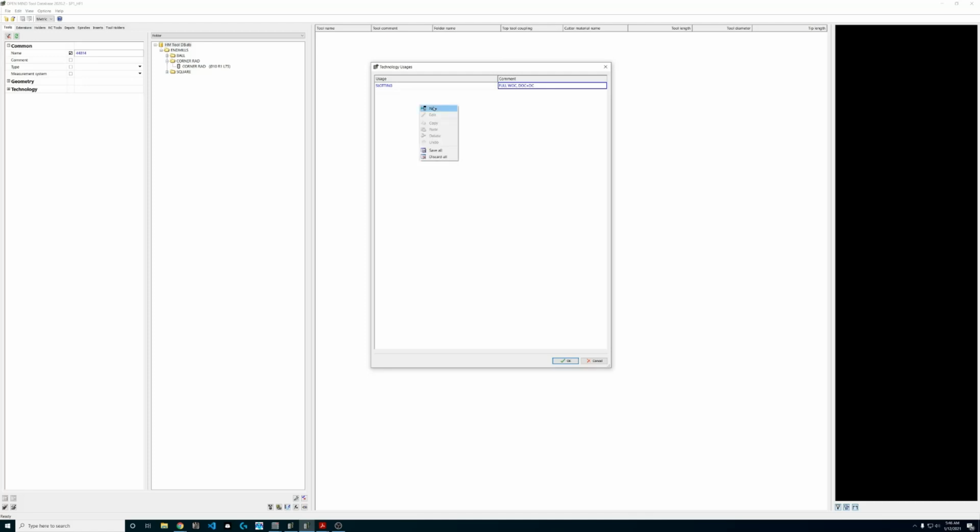Since we're just going right out of the catalog, the other 2 parameters given are profiling. Sorry, no space at the end anywhere in the tool database. Add a space on the end, hyperMILL angry. So no spaces. And we're going to say this is side milling at, they're saying anything less than or equal to 0.5 DC, and we're going to say at 1.5 times DC. So they're basically saying anytime you're using less than half the cutter and less than or equal to 1.5 times the cutter's diameter AP, you're in a profiling application.